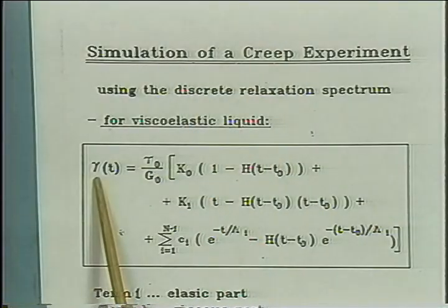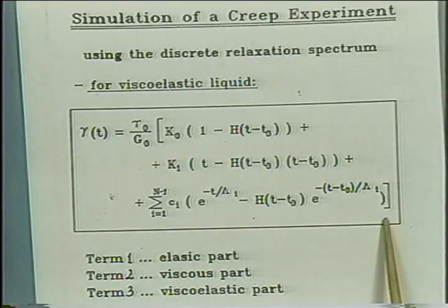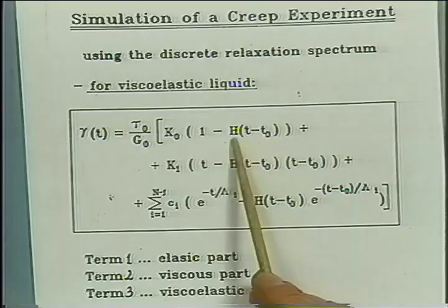That's all set, and the mathematics for doing that was developed in the 50s. You can find that in numerous textbooks. Simply, you could model the creep experiment. You could take the Boltzmann equation, put in a jump in the load, and calculate the time-dependent strain response, and you will find this type of response given here. Those h's, by the way, are Heaviside functions.